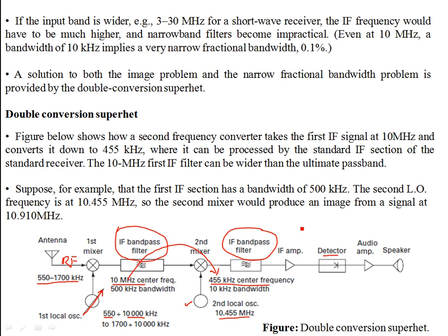At high frequency, you need more sections of bandpass filters, which might be impractical to build. For example, for a 0.01% fractional bandwidth, the crystal or a coupled resonator bandpass filter could be very expensive instead of an LC bandpass filter. So we can avoid these double conversions and the mixers.